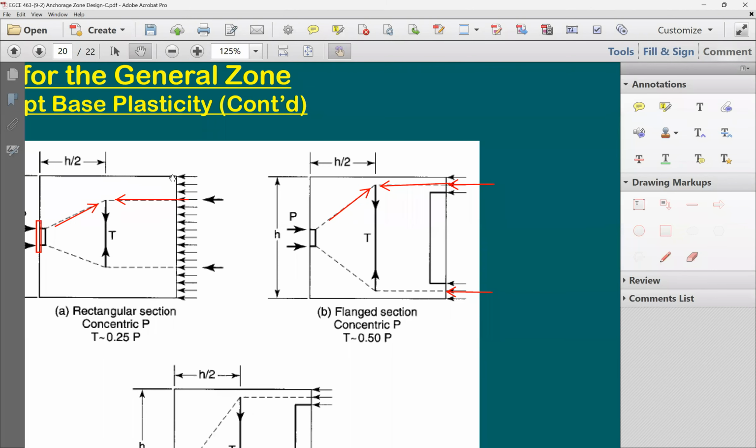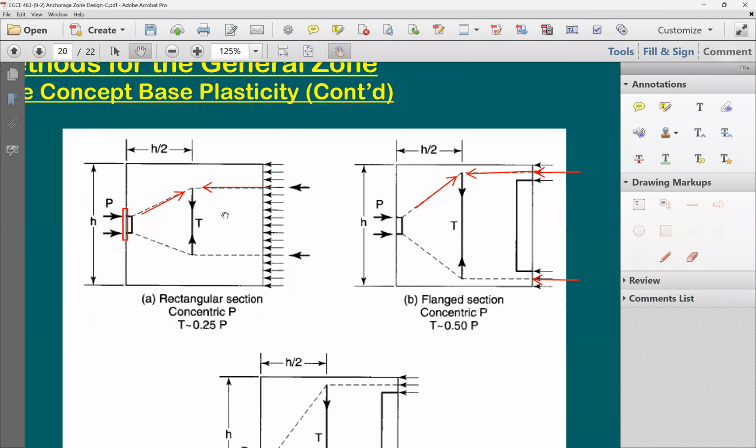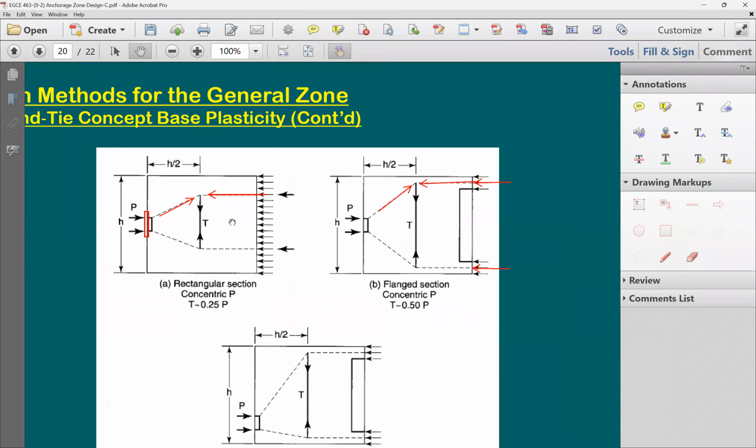And here I have a completely rectangular beam, and I'm going to have uniform stresses on it. But in here it's going to be different. The force is going to be pushed up and pushed down. This is the reason when you have an I shape like this, you come here at the end of it and you provide a solid piece of concrete to reduce the amount of stresses and forces on it.